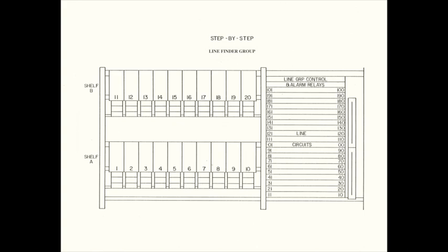That criterion was that in the busy hour of the busy season, 1.5% of the calls should be delayed greater than 3 seconds. Telephone company traffic engineers projected the busy hour loads per line finder group and applied these to traffic capacity tables that predicted the amount of dial tone delay for a range of loads and quantity of line finders. It was not unusual to see only 12 to 14 line finders equipped in small town central offices. It is interesting to note that in the busy hour, in order to meet the service criterion, a line finder could only be in use for 60% of that hour and needed to be idle for the other 40%.